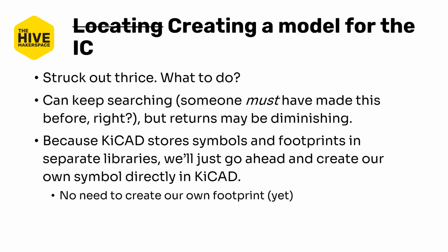So instead, what we're going to do is make the symbol in KiCAD directly. Symbols are relatively easy to make, and they're less prone to errors than custom footprints are, but they can be tedious with many pins. It's totally doable to make them without waiting for Ultra Librarian or SnapMagic, especially if they're only like 6 pins like this one is. Once you get good at it, this is like a breeze to do. The real problem is like microcontrollers with 100 pins. Those suck.